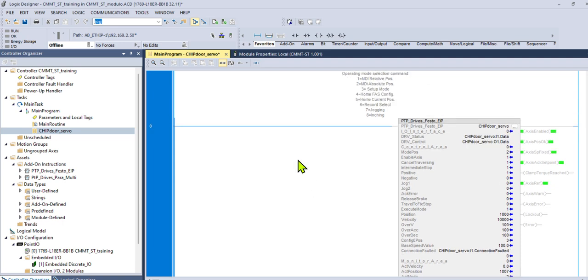There are some comments that I like to put in right above it under the edit line. And these can be found in the application note too. So I copy them out of the application note and then paste them here. There are different modes we can run this in. If we put a 1, so this mode position right here, I got a 2 in it now, and that means I can make moves in absolute position. Put a 1 there, I can make moves in relative position.